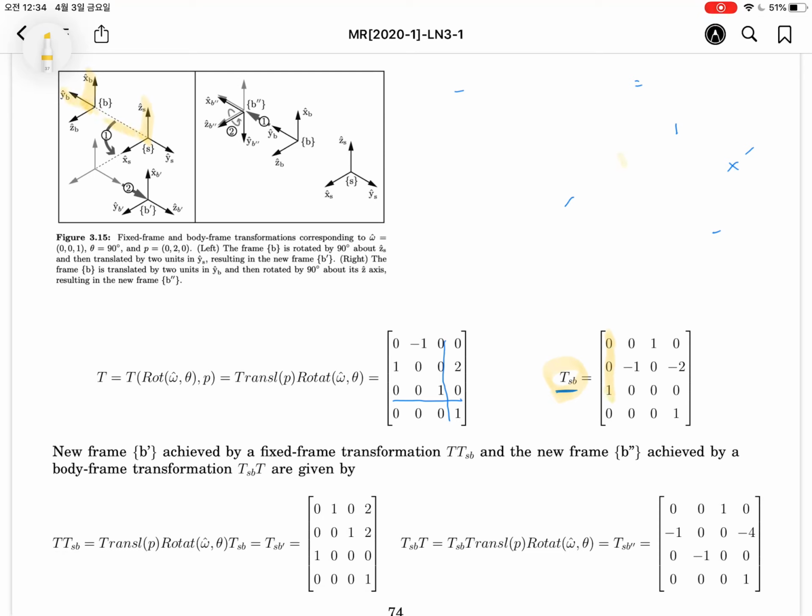And y can be read from the minus y-axis, so 0, minus 1, 0. Z is aligned with the x-axis, so 1, 0, 0. And then this is 2 units in the minus y direction, so 0, minus 2, 0, and the 3 zeros and 1 as added. Okay, this is the operator. This is the representation. Let's multiply this T matrix on the front side and lateral side.